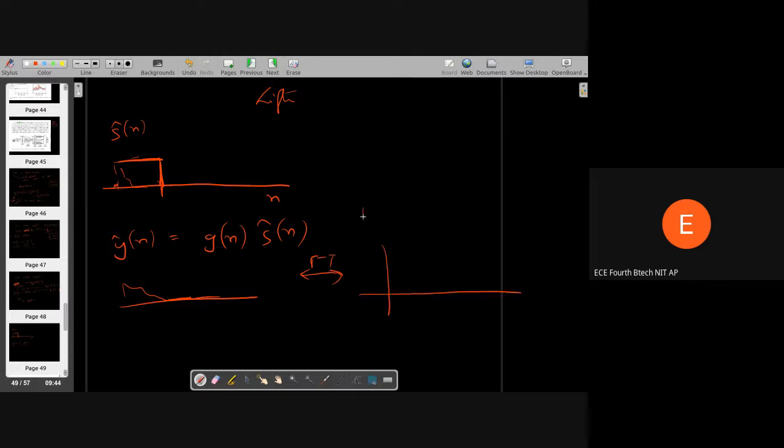Whatever the Fourier transform gives, a log magnitude spectrum, we find that this represents the envelope of the speech spectrum. Indirectly, it represents the vocal tract, the system. We say H hat because we don't know exactly how to separate out S hat n equal to E hat n plus H hat n.